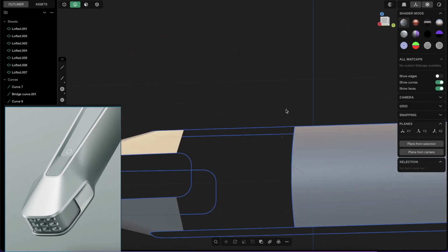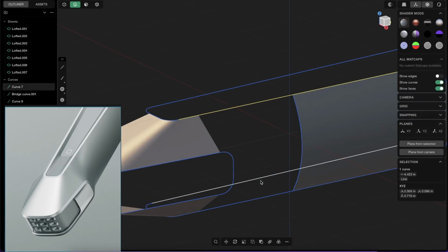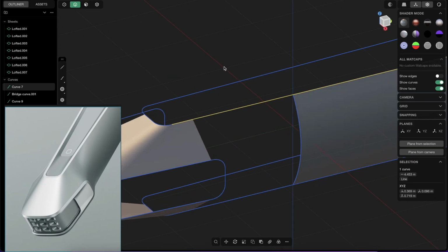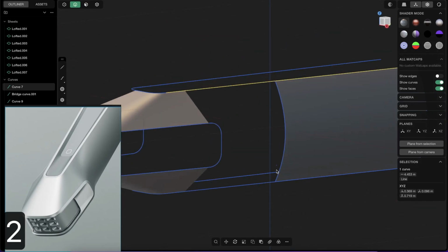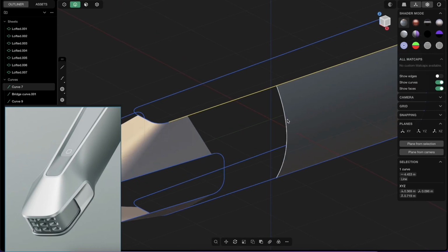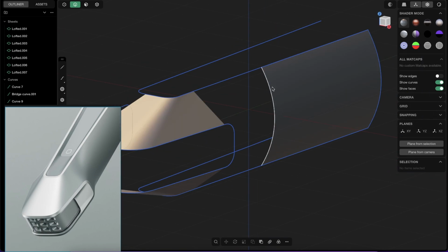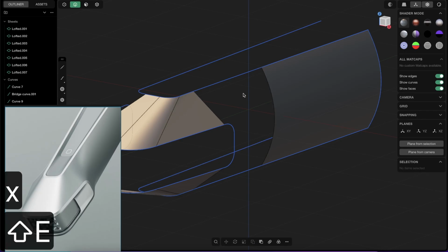And now let's go to this point. So first of all, you see that we have this one long edge, a line at the bottom and at the top. And again, we first have to break it down where we have this curve at this point. But here it's simple because everything is intersecting. Press 2 and with shift click, just select those 3 curves and Alt J to unjoin. And this way, everywhere where they intersect, you will cut them also. Now, very important, delete the curve because we need the edge here.